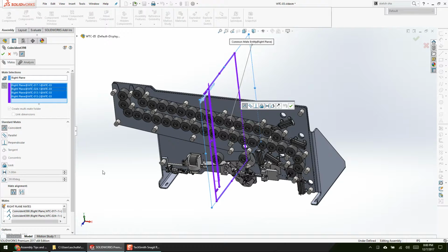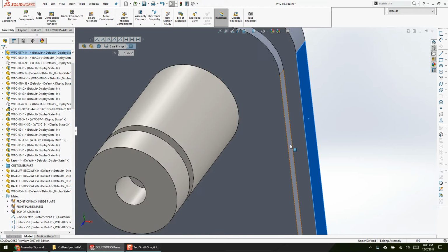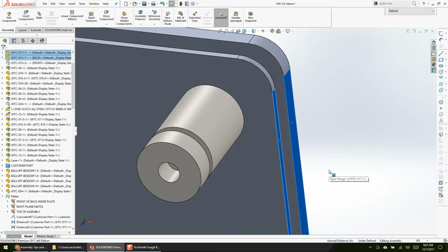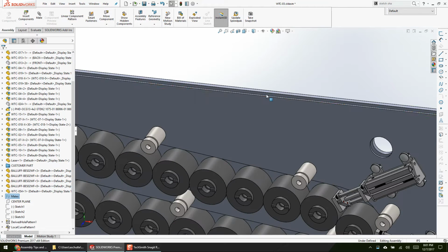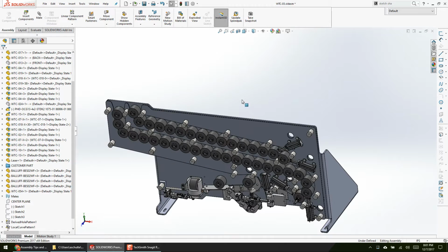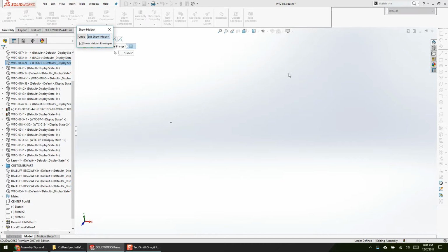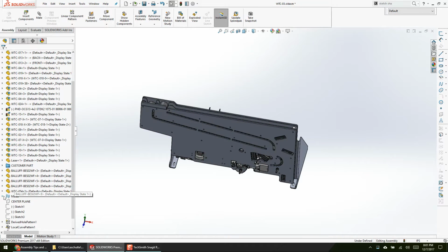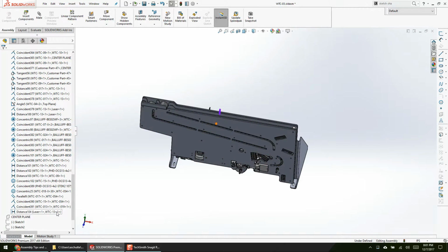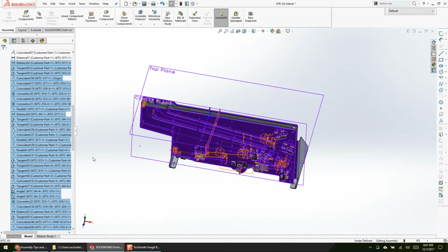Like ever, right? So that's superior to me than trying to mate these edges up, because those edges can change, those edges can fail, or those faces, edge of the sheet metal. I've got to be careful, because this is an edge in SolidWorks, right? So we'll show those components again. Right, so I've got some that looks like this, and of the number of parts that I have, again, remember, usually you have 3 mates per part.